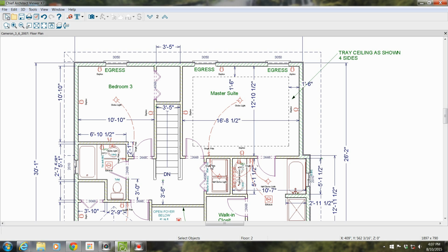I talk about that in my book, The Dimension Bible for Do-It-Yourselfers and Remodelers. I talk about the space that you need for this. I mean, in a new home, and the architect's building it, he knows what he's doing. He leaves ample room. But if you're in a remodeling situation, you got to think about the way the door comes off and the door opens, because it's bifold stack, and you've got like about a foot of space here. So does it allow this door to open all the way? And if it's right-handed or left-handed, so you've got to account for all that.